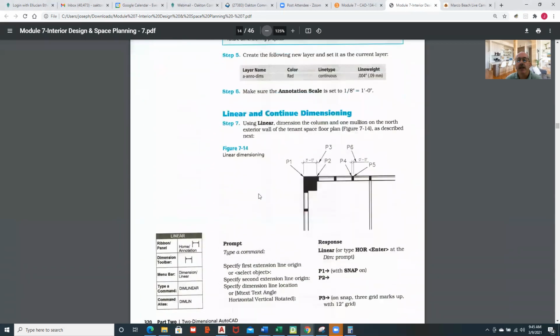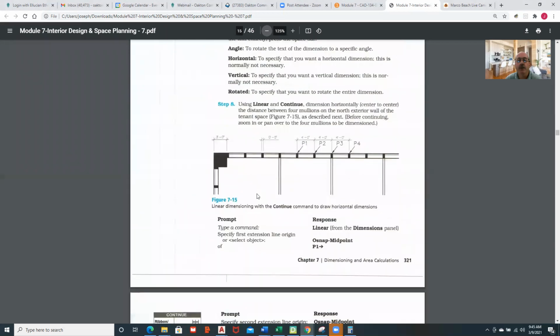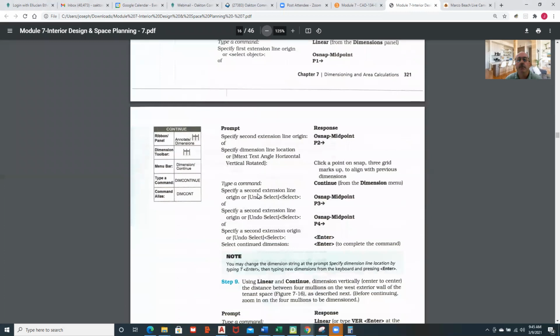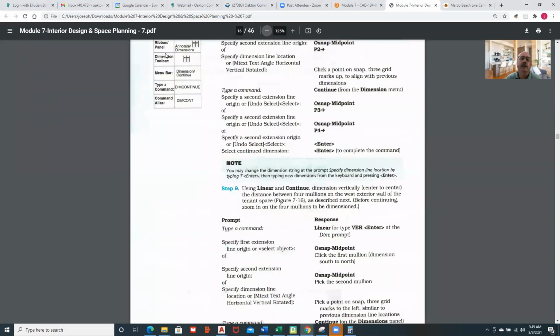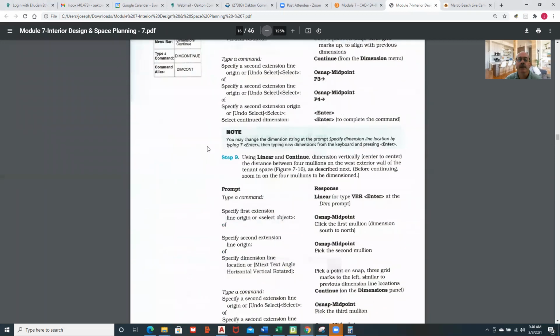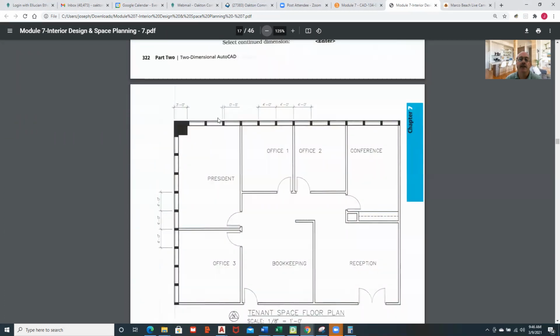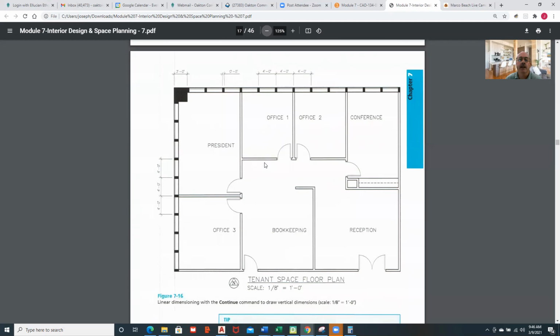All right, and so I'm going to have to move along a little bit because we've got 10 minutes before I've got to get into some other things. Let's see. Continuous dimension styles will just have the dimension continue from the last endpoint. These are really very basic things. And so it'll look like this. You put one dimension on, and then you use dim continue, and it'll keep them all lined up just like that and continue one from the end to the next.